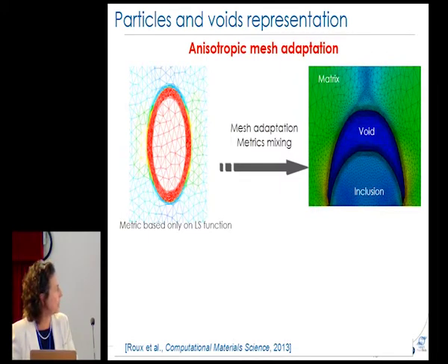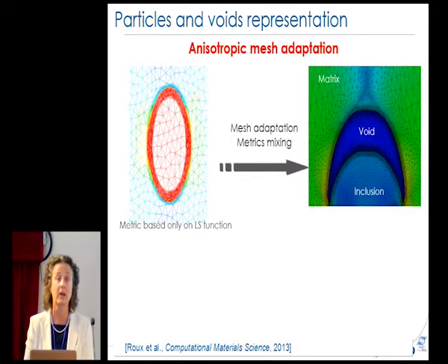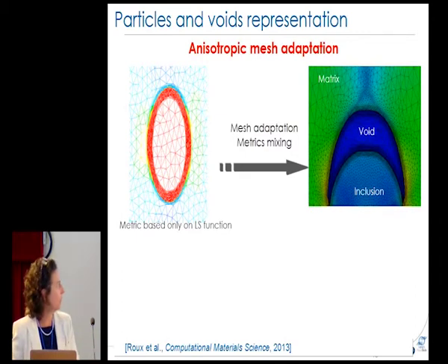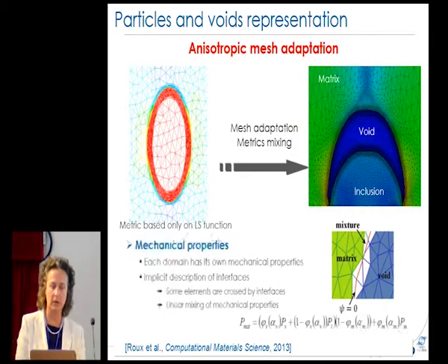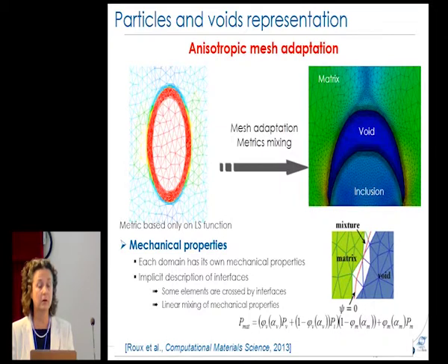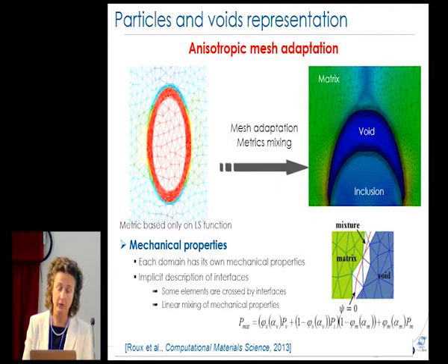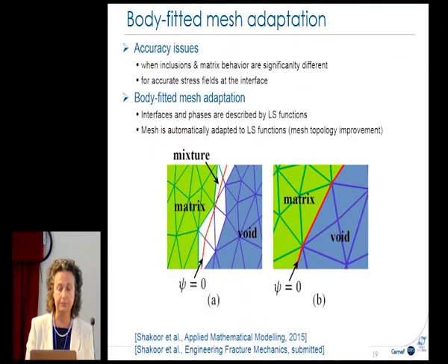But if the particles are close to the interface, there is a specific problem with a very large grain together with a very small grain, and this is a big problem for the industrial partners. This is an example with a nice distribution of grain size, and during the heat treatment, we can get a heterogeneous grain size, and this blue grain is a big problem for the end user.